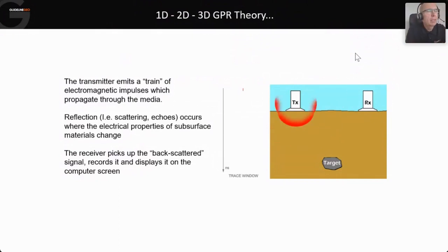Just go back one there a second. So that signal is semicircular at this point, and it's starting to expand outwards. You will get some signal traveling between the transmitter and the receiver antenna. That's one of the first things that's going to hit the receiving antenna, this direct wave. This is what we often refer to as the first arrival, the direct wave, or the air wave. And you can see the response now on the meter, so to speak, on the recording. That's our first pulse of energy that's actually hitting the receiving antenna.